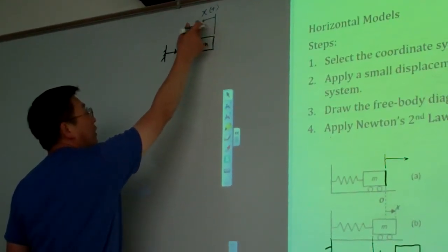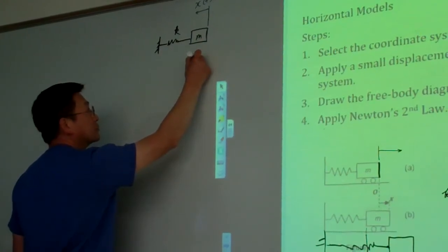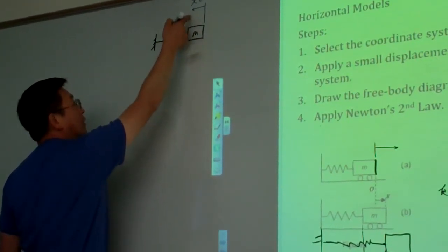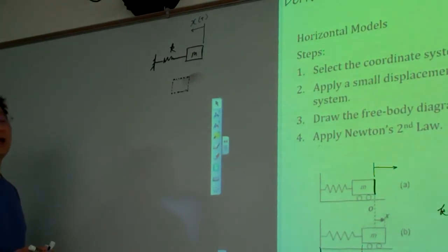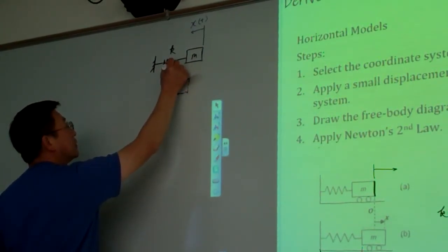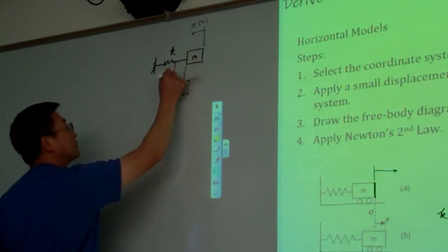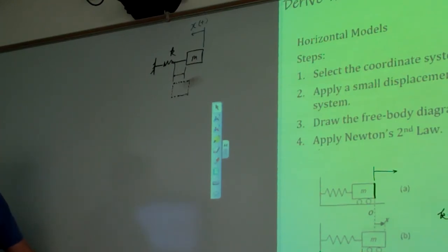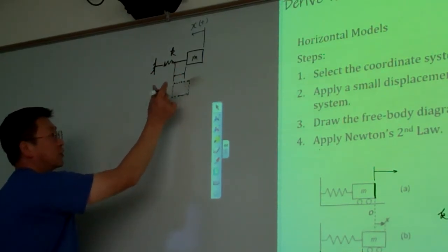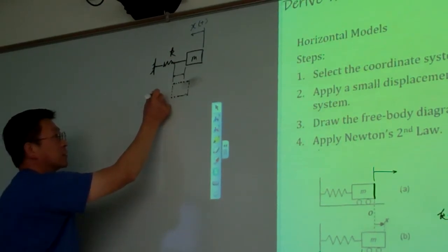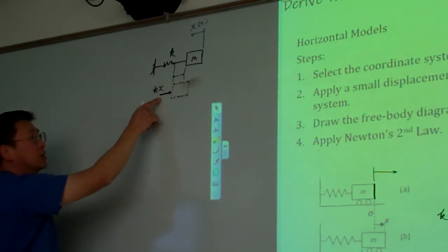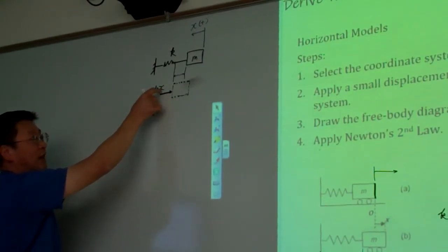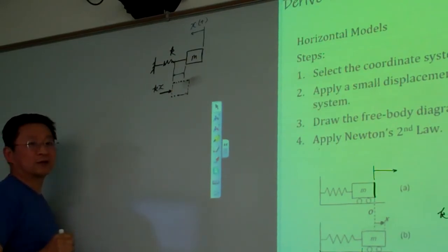For this case, we simply follow our selected degree of freedom and move the mass block along the direction we pick, so the mass block moved to here. Compared to the two distances here, this is the amount the spring is deformed, being shortened. If the spring has been shortened by that much, then on this free body diagram the spring tries to stretch back. So the spring exerts a force of that amount, but the direction is pushing that way, right?